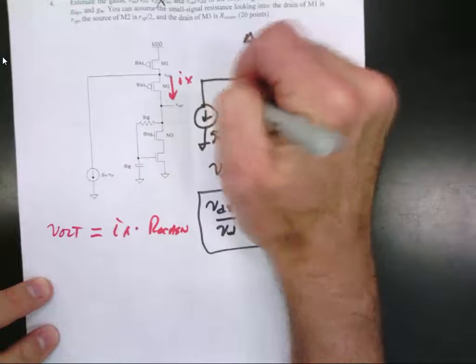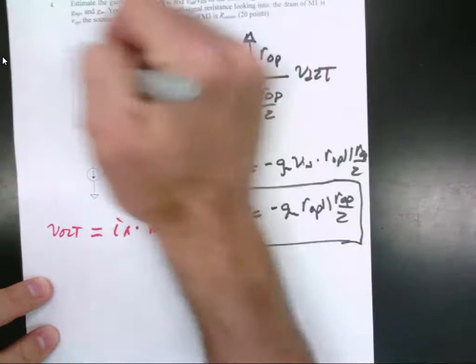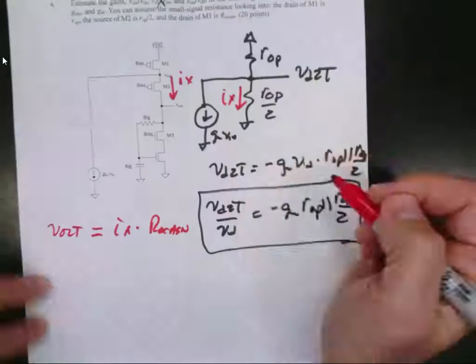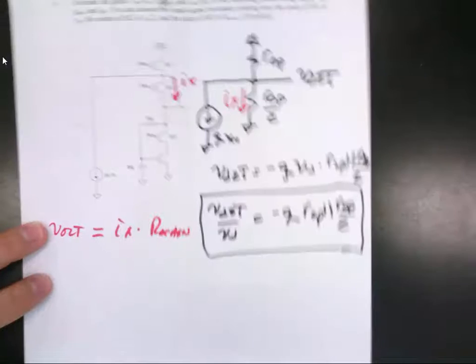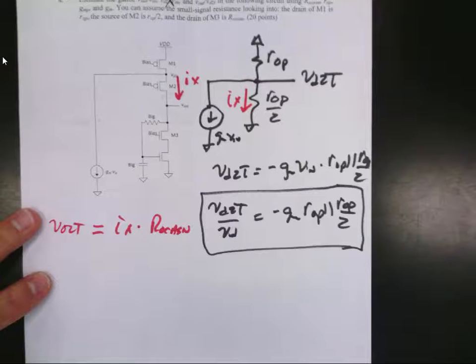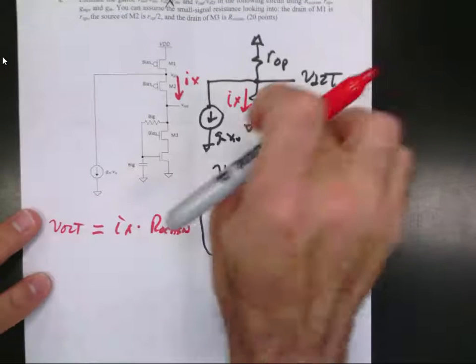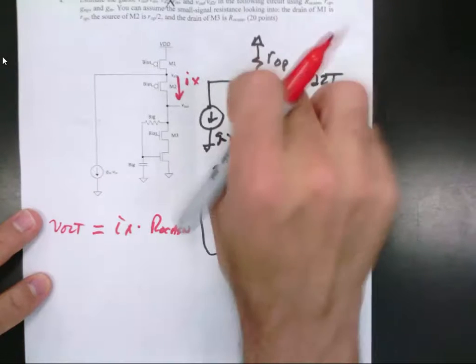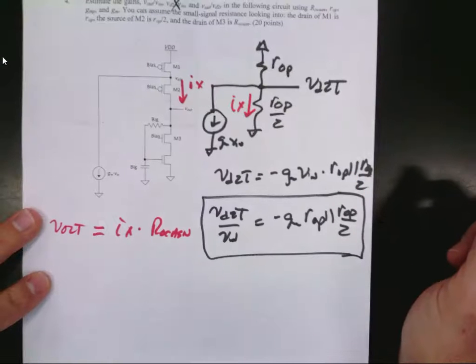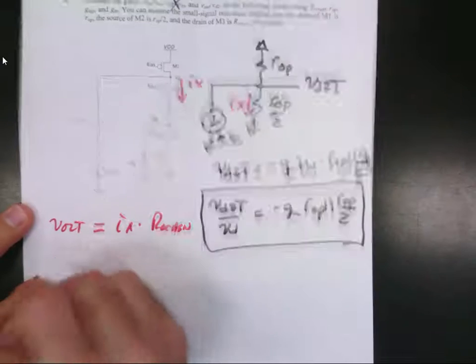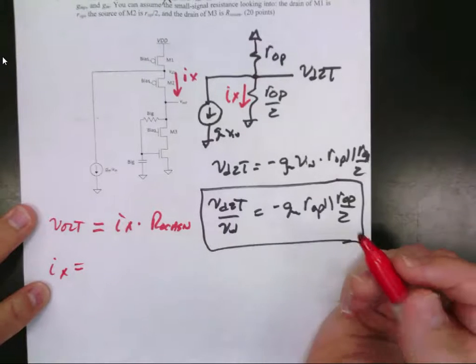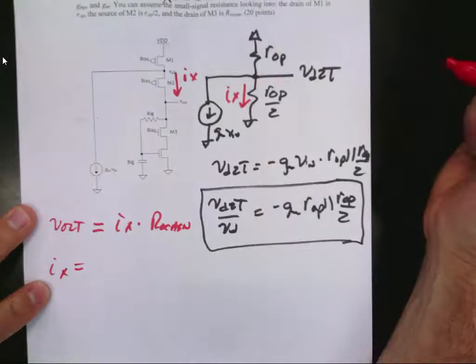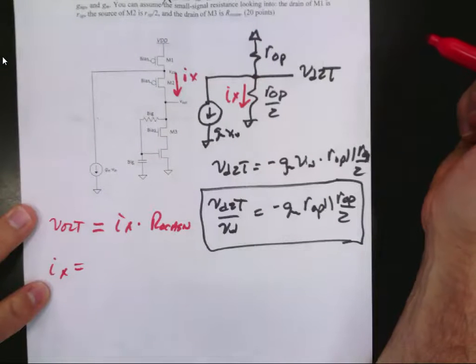That's the current through there. So we get a current that flows through here and a current that flows through there. Of course, it's going to be negative if I put these currents going out because all three are going out. How do I calculate the current that flows in that resistor in two parallel resistors? From circuits 1, like the third week. What is this circuit called? Current divider.